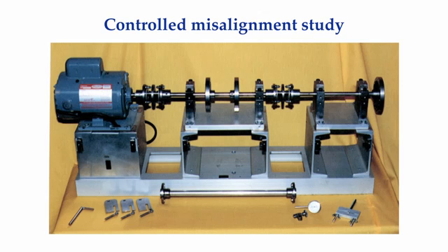As shown in the photograph, the demonstrator consists of a 1/2 horsepower, 120 volt single-phase motor running at 3,590 RPM. It is flexibly coupled to a center shaft with 2 balance discs. The center shaft is then flexibly coupled to an outer shaft with an overhung balance disc. I carefully balanced the center and outer shafts to minimize any unbalanced influence in my experiment, so I could hopefully only see what effect misalignment had.